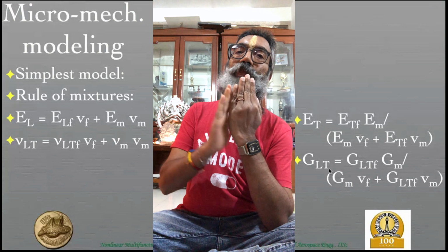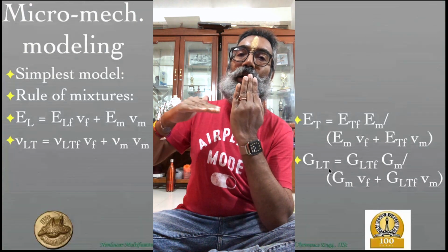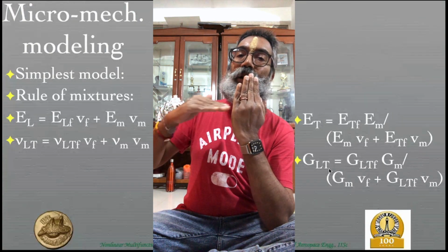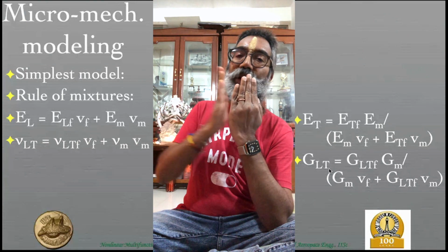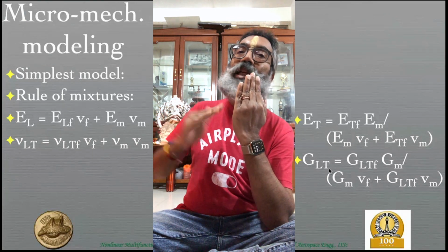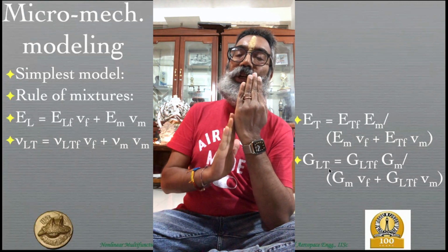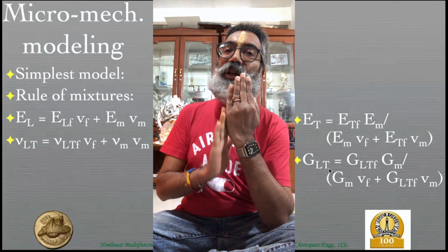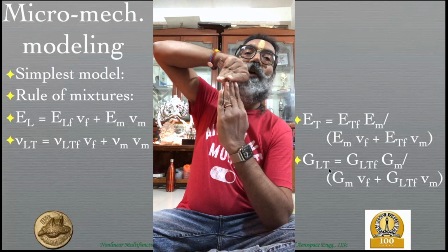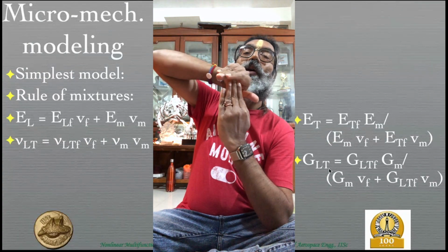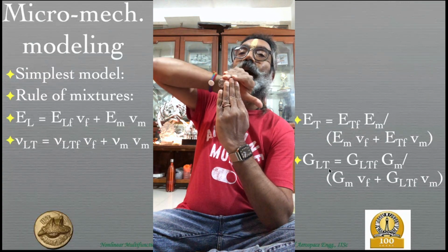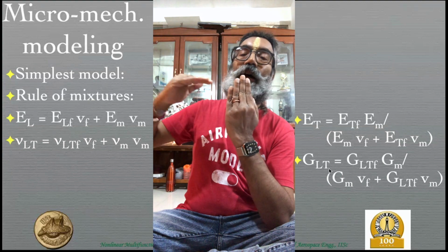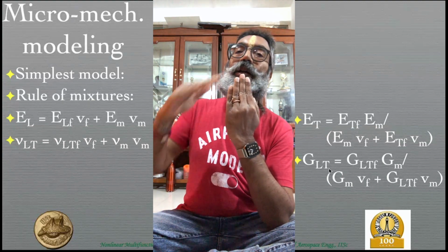Why is this the T plane? Because its perpendicular direction is both perpendicular to the fiber as well as to this plane. So it's acting on the T plane in the L direction. It is a shear stress, which we will denote as tau subscript TL. In the same way, on this face it's the L plane on which the stress is acting in the T direction, and therefore we will call it tau LT.